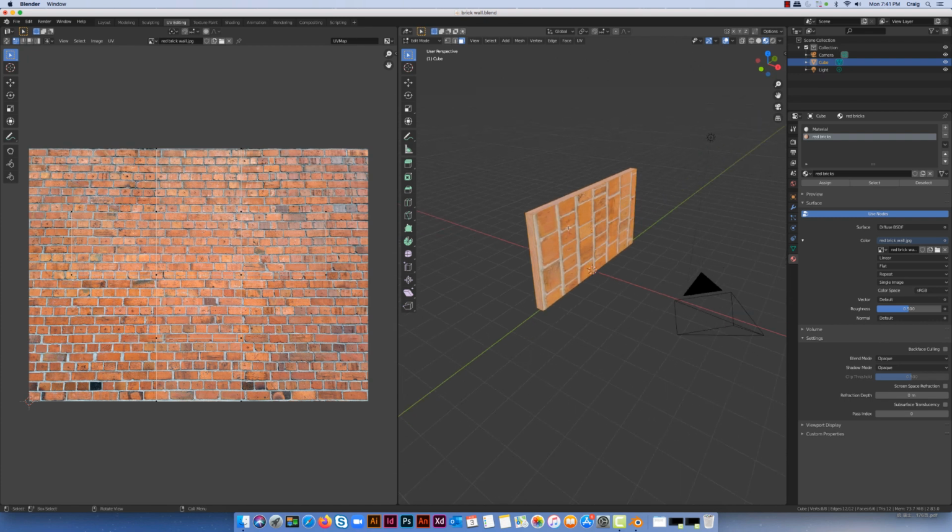So in this case, I'm going to choose this face, and you can see here how it's this part of the object selected here. And what I'm going to do is essentially unwrap it. So I'm going to separate it from the wrap which it came in. I'm going to do that just by right clicking and clicking on unwrap, and it will now just place the face across the entire image here. And if you look over here on the right hand side, you can see all of a sudden that everything's kind of lining up and the bricks are looking better.